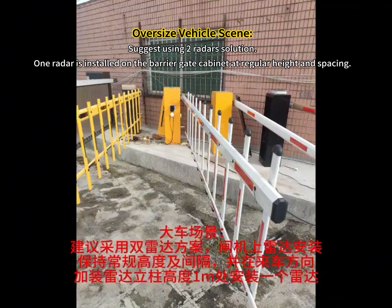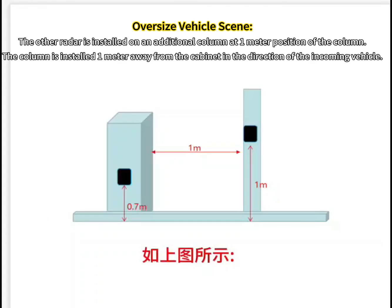Oversized vehicle scene. Suggest using two radars solution. One radar is installed on the barrier gate cabinet at regular height and spacing. The other radar is installed on an additional column at 1 meter position of the column. The column is installed 1 meter away from the cabinet in the direction of the incoming vehicle.